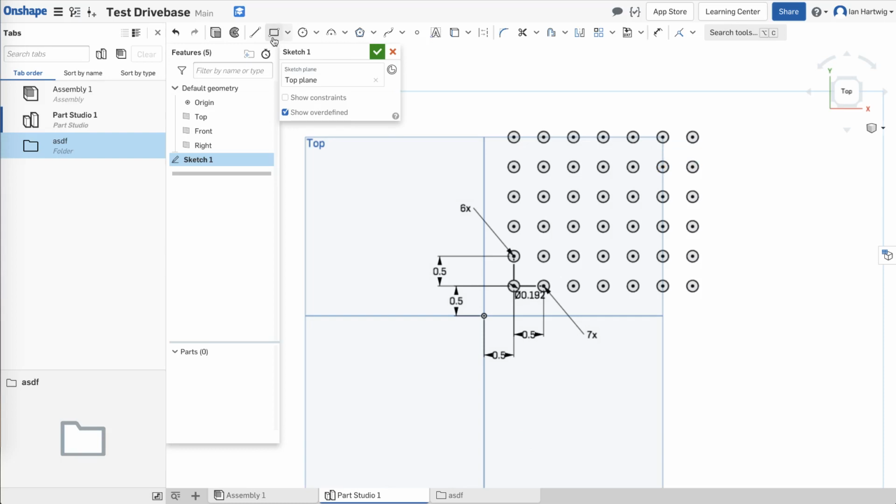Okay, so let's define the outline metal of our bracket. I probably should have mentioned, we're going to do a right angle bracket instead of a T for this application. So I'm using the rectangle tool now, the corner rectangle over here. This is useful because you can define the two corner points and, unlike drawing lines, it will automatically put in your 90-degree corners.